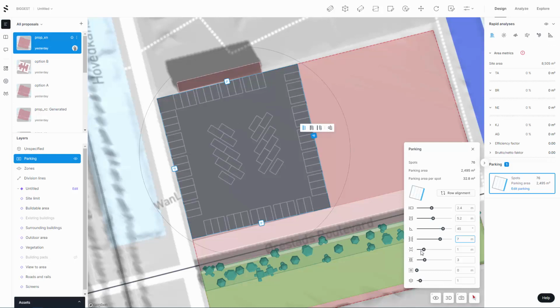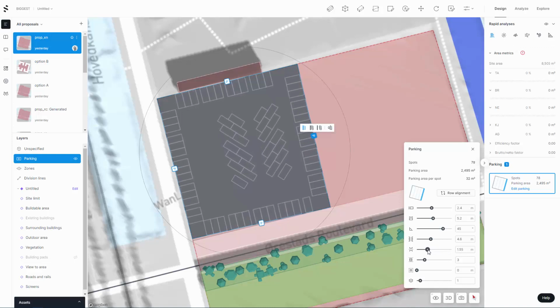We have column width, so at the moment you'll see between each bay there's space, potentially four columns, which are always fun. Again, you can change that depending on the grid that you would typically work for your building. So you can see it's getting pretty tight in there. Here, column widths here. So we crank up those column widths depending on the structure above.